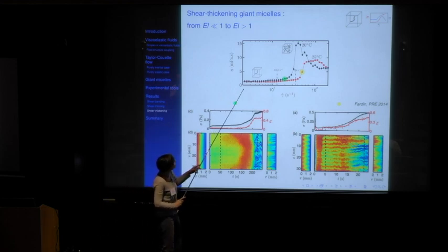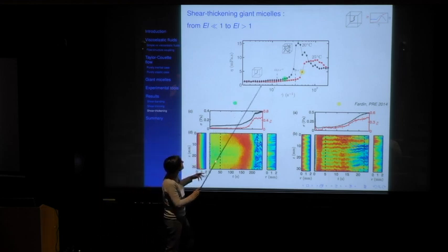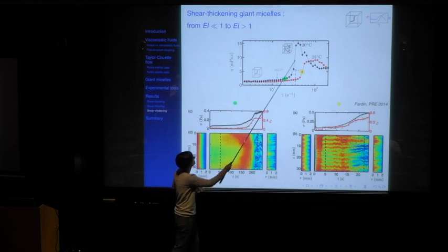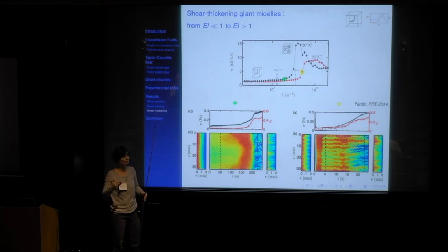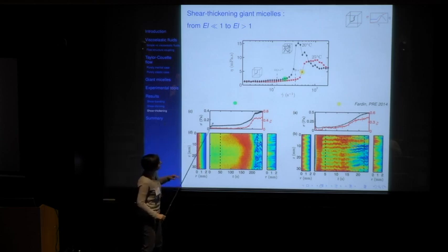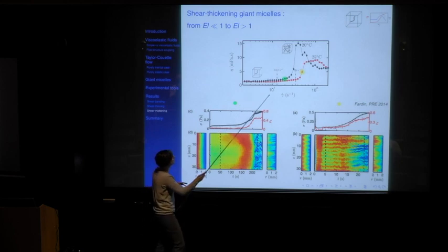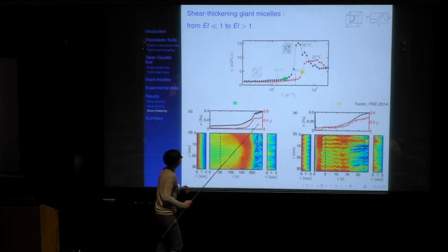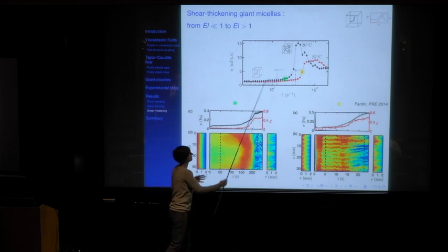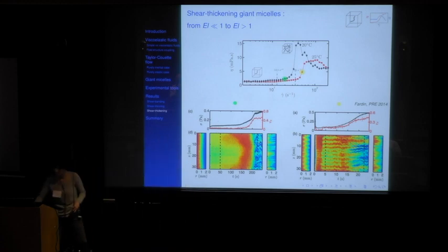An important point also is that when you shear the system in this region here, in this viscosity jump, you need an induction time to build up the new elastic phase. So I just want to illustrate this case with two different shear rates. This is the same sample at two different temperatures. We apply a constant shear rate and we observe as a function of time what happens. So here is the first case.